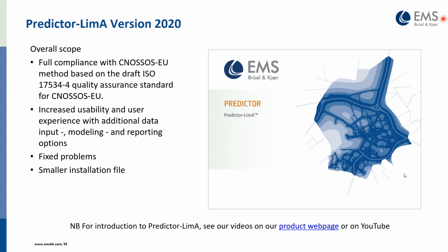If we look at the overall scope of the Predictor LimA version, we put a lot of effort into the CNOSSOS-EU calculation method, and it's now based on the draft quality assurance standard, ISO 17534-4. Part 4, and that includes about 28 test cases. So we can prove that we calculate according to this CNOSSOS-EU method.